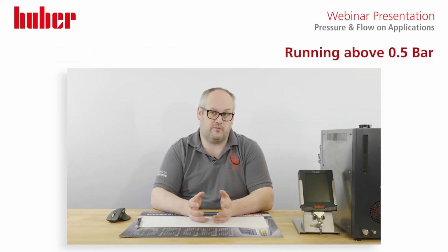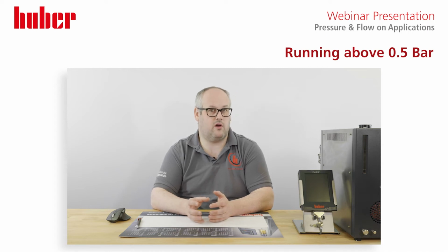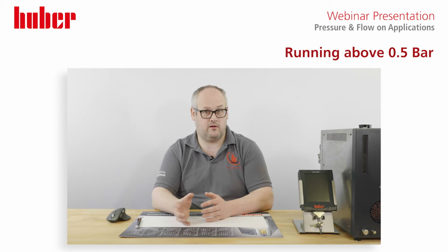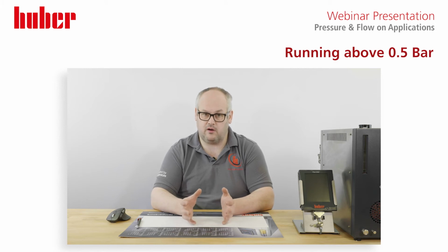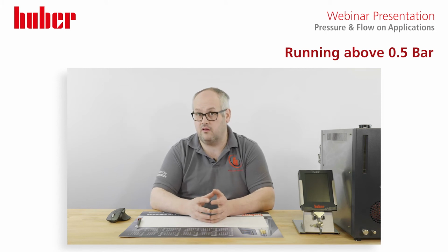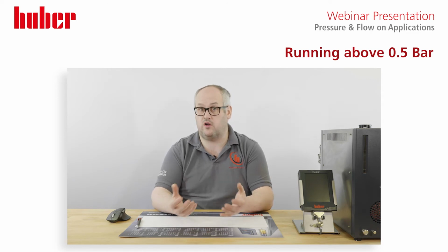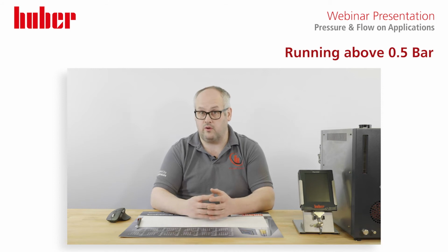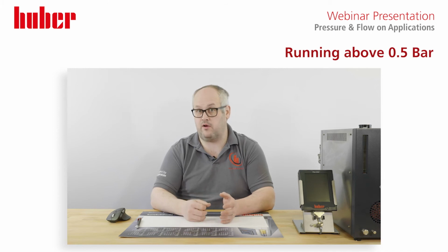So we've looked at various concepts here, and we've shown that we've actually run systems with a pump pressure greater than half a bar on glassware, where manufacturers say you shouldn't exceed half a bar. But the key fact here is none of our systems are truly sealed systems. If we were to run what I'd call an externally open machine, which is a bit like a hydraulic line on a tractor, the fluid cannot expand. There's no room for expansion in the system. So when you apply a pressure, say a piston moving against it, it would break.